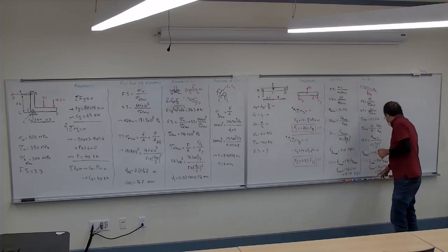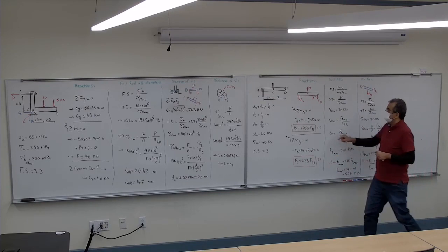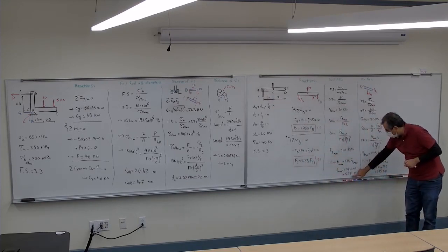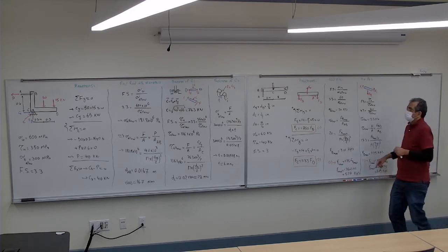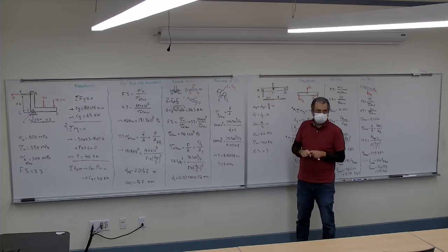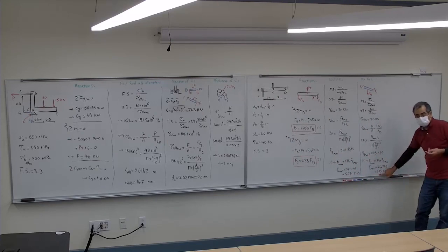If it becomes 5.15, it's gonna break at the B. So if it is 5.27, it means that it's already broken at 5.15, B. So if I put force here and increase it, the B will break before the AB breaks. Correct? So between these two, which one can I use? The smaller one. You got that?